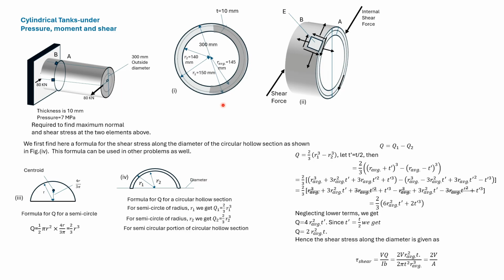Determination of shear stress for such a case is a bit involved. And here we look at the issue before we start solving the problem. This was discussed previously in the chapter on shear. Here we discuss it again briefly in a slightly different way. The statical moment is given by the area multiplied by the distance of the centroid.